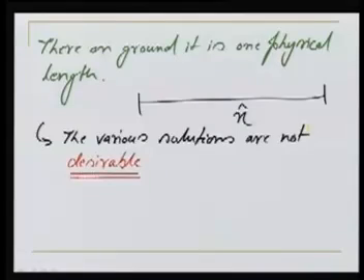Now, to answer this question, we will go for the technique of the least square, because there on the ground is one physical line. It has a length between 2 points. It can't have multiple lengths or multiple estimates as we are seeing in the previous slide. It's one line, so it should have only one value. So what we will try to do, making use of all these observations, which are desirable because we want to have redundancy in the observations, is estimate the best possible solution for that line, or the best possible length. Okay? How to do that?